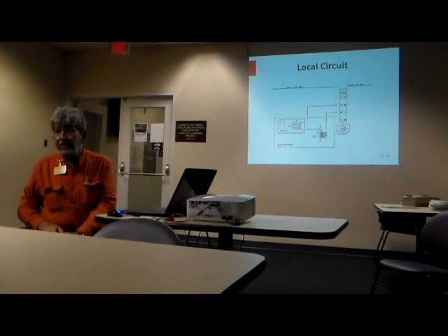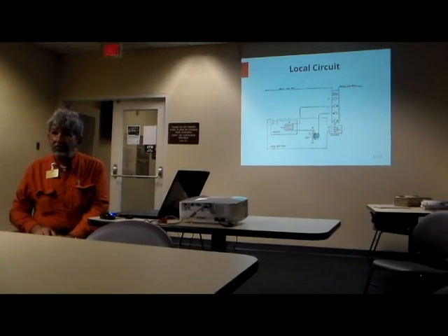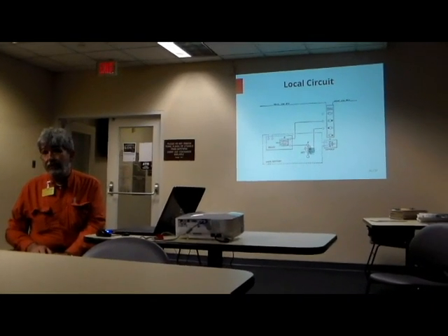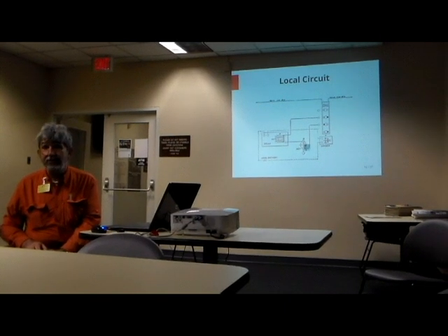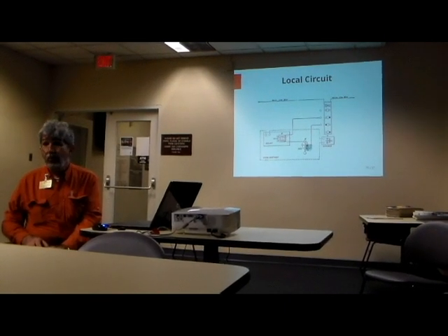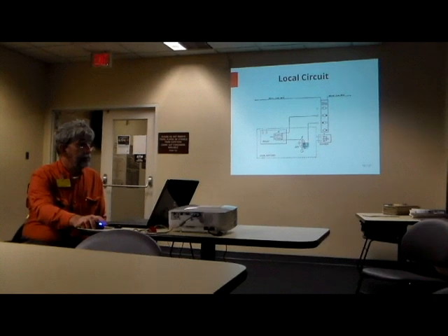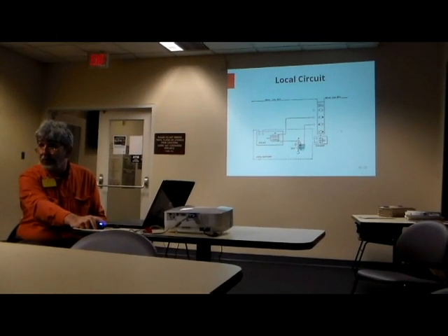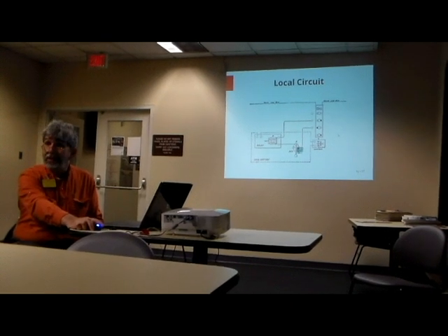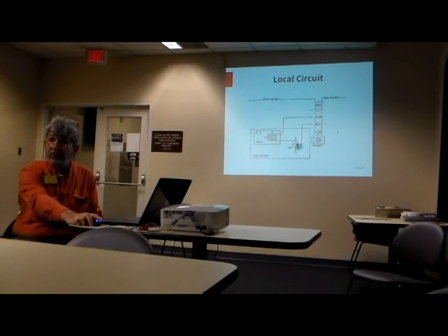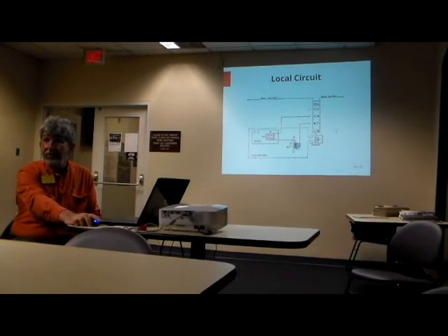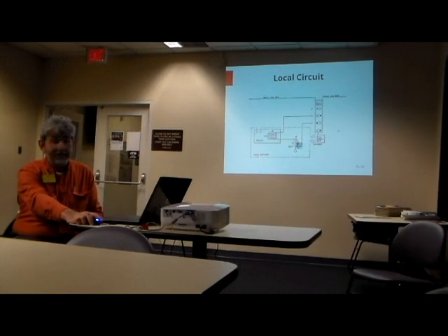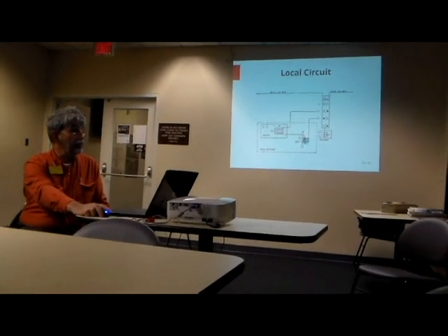a volt. Now the battery wasn't real generous with the voltage it produced, but it was wonderfully generous with the current. It produced plenty for the job, and that's one of the reasons it worked well for so long. But initially, they were the only batteries you had. You needed one battery for each volt you needed for anything. And that's why the local sounders are only 4 ohms, so they could run on only 1 volt at a quarter amp.